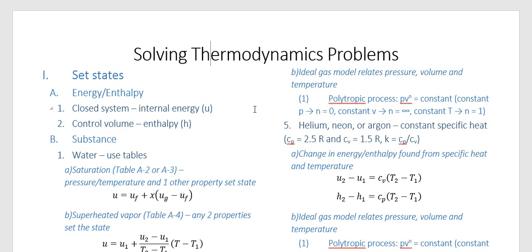This document serves as an outline or a flow chart on how to solve thermodynamic problems. Okay, and this works for most problems that you're going to experience within thermodynamics. So basically, the first thing you want to do on any thermodynamics problem is what I call set the states. Okay, and what that really means is find the properties at each location or each state in the system.